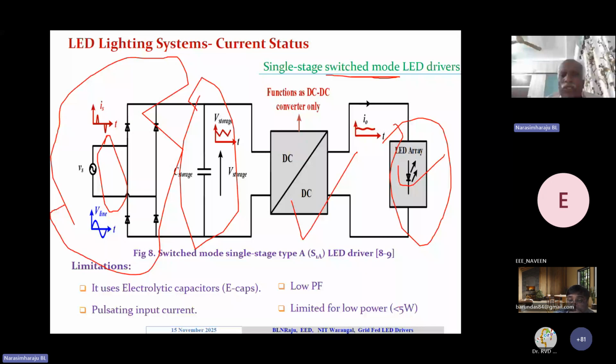If you want to increase the wattage to a higher power rating, a simple step down converter may not be suitable, for stepping down roughly 190 or 200 volts DC from the 230 volt single phase AC grid to a very low voltage like 12 or 20 volts.